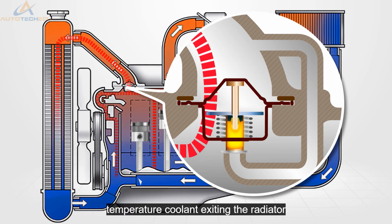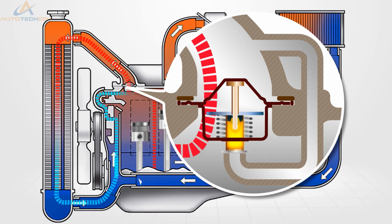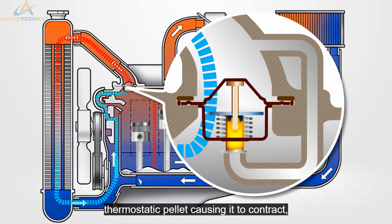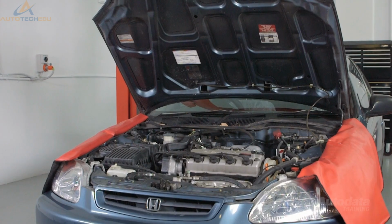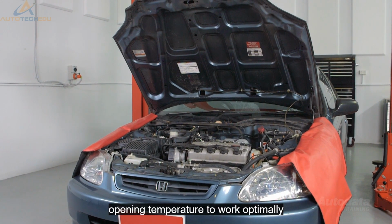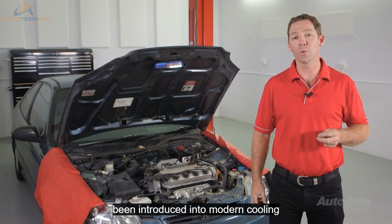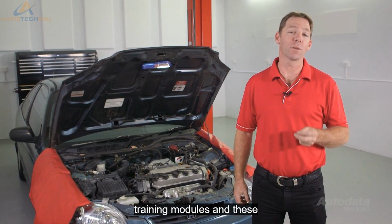Low temperature coolant exiting the radiator will be pushed through the engine, finally reaching the thermostat. This coolant will absorb the heat energy from the thermostatic pellet, causing it to contract, allowing the return spring to close the valve. This cycle of operation is constant in a correctly functioning engine. Manufacturers designate the thermostat's opening temperature to work optimally with the engine design. Electronic thermostats have now been introduced into modern cooling systems and are controlled by the engine control module. Keep a lookout for our training modules on these.